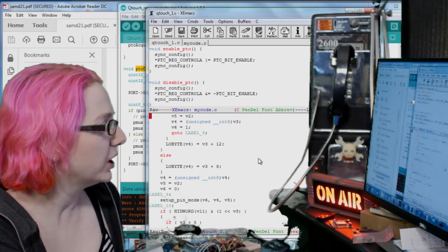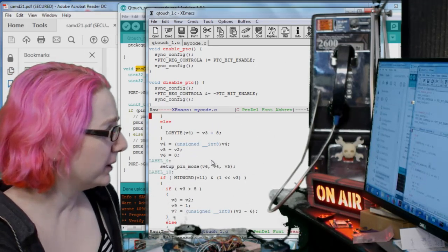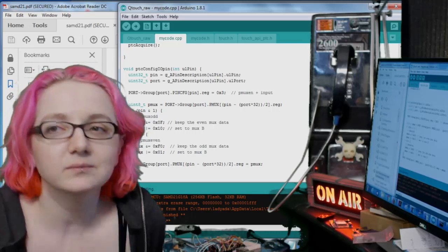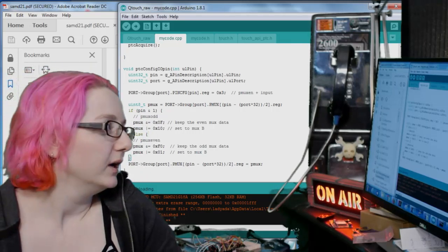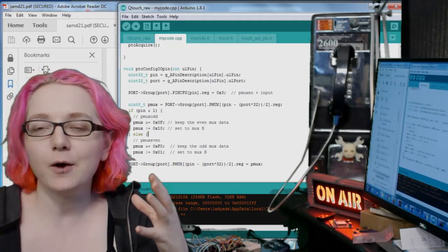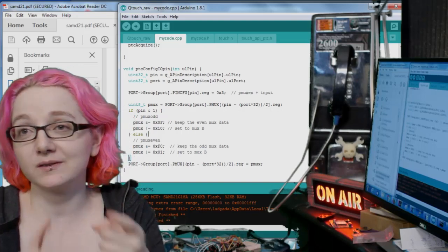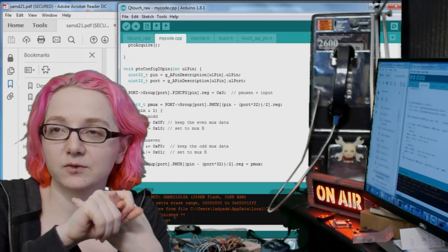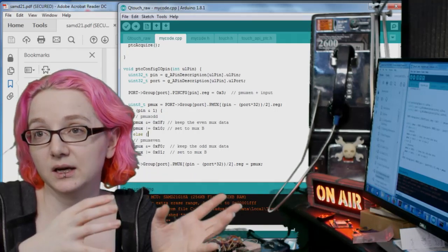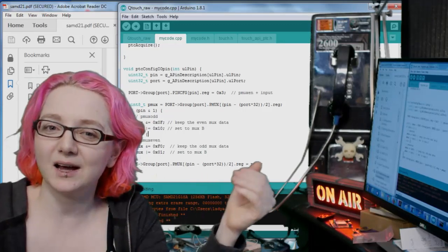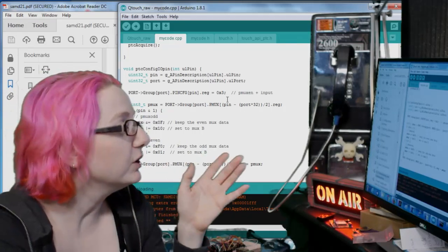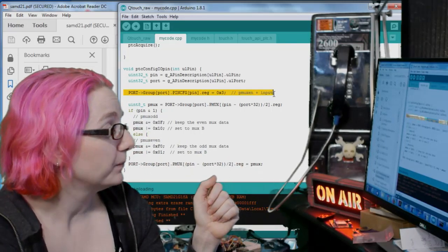It just got kind of messy in this code. There's a lot of unknown variables and a lot of bitwise stuff and labels. And I was like, well, look, I actually know what you're going to do. If you have a function called config IO pin, it's like every config IO pin from now until the end of time on a microcontroller. You're going to set the direction, the strength of the pin, if necessary multiplexing, making it actually use the peripheral you want. You basically have to tell the peripheral what pin to use and also the pin what peripheral to use, right? You have to set both. So I just rewrote that from scratch because it's pretty straightforward.